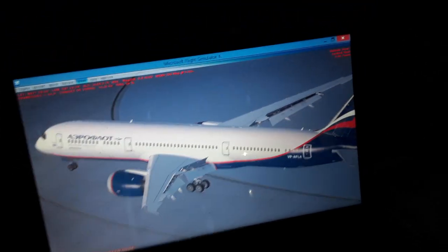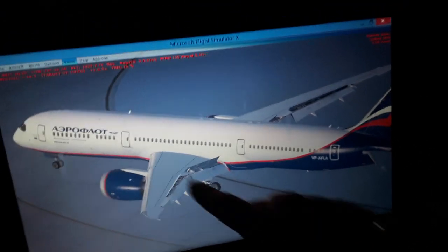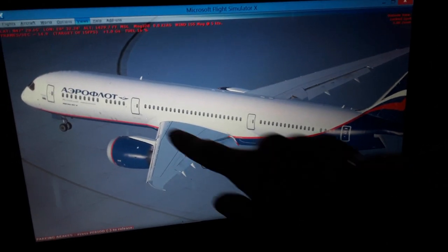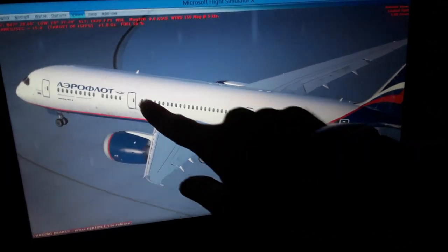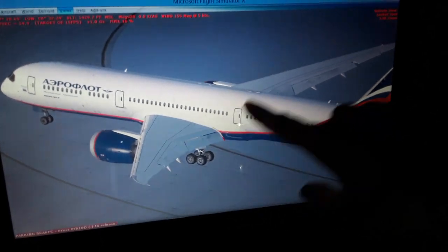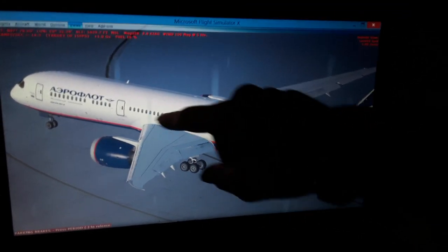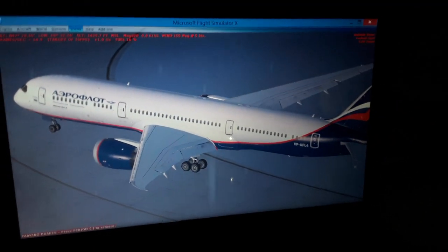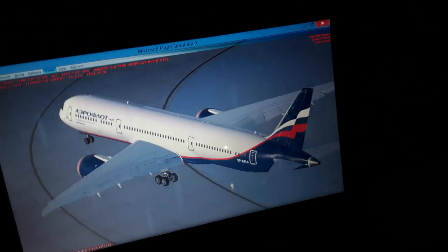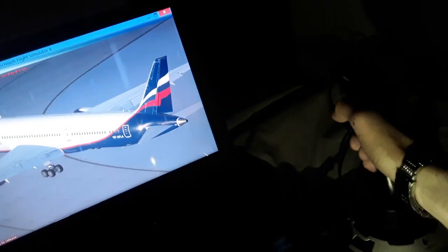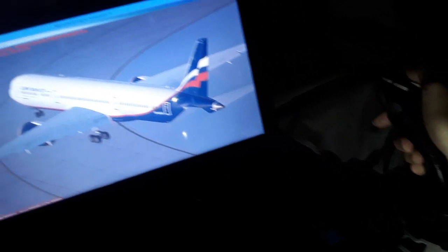Also, the top surface of the wings has more curvature, is more curved. So using Bernoulli's theory of fluids, the airflow moves much faster above the wings, so we have a lower pressure, which sucks the aircraft weight and wings up into the air. So these are the basic principles, the aerodynamics, as you can see. Flight controls here for climb and descent.